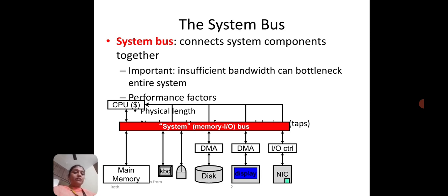Because the devices share a common set of wires, that is a common set of bus, at any given time only one device can send the data. All devices simultaneously listen, but normally only one device receives. Only one device can be a bus master at a given time, and the remaining devices are slaves. The bus master controls the bus and can be either a sender or receiver.